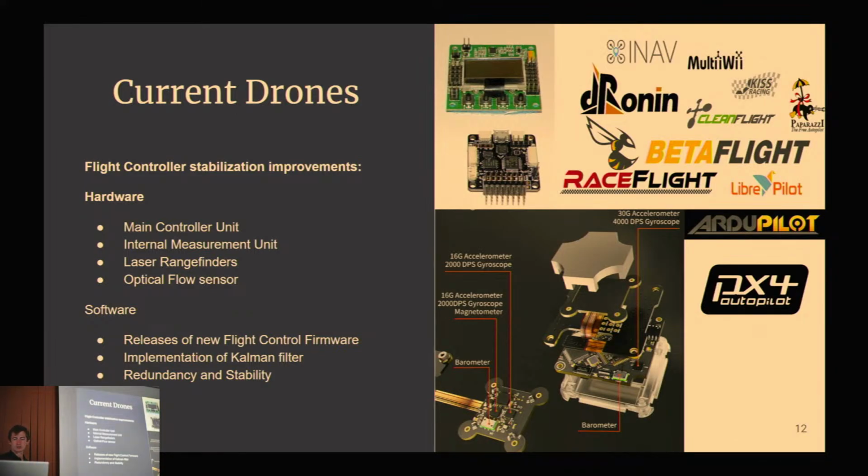What was upgraded also, of course, people very fast removed the LCD from the flight controller because drones are very likely to crash, and the LCD was I think the first thing that broke during any descent, which were simply too fast. Moreover, people put faster IMUs and faster MCUs on board to make all the algorithms run 2 or 3 times faster, and it was possible to fit them even on the small drones.